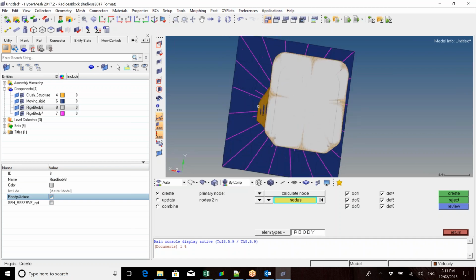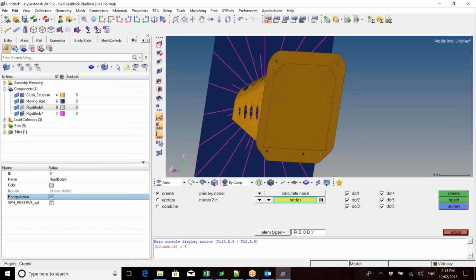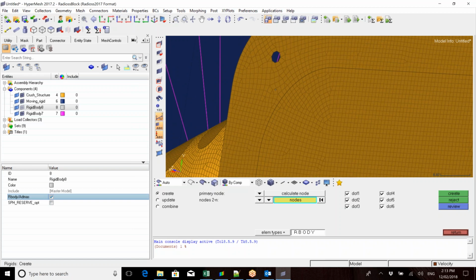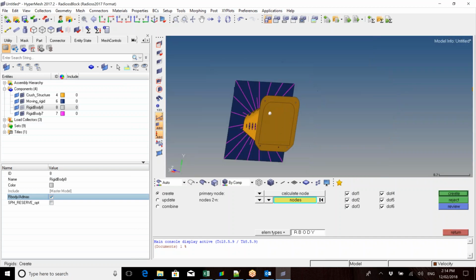So for this as well, the rigid body on the back of the crush structure is connected only on this side plate here. As you can see, there's an edge flange when the screen comes up. There's an edge flange here around the edge of it, and you can see the line there because on their structure this is actually enclosed in. So I've only rigidized the very edge of it, but when doing this, making sure that you set it up correctly for your vehicle, and correctly if it is properly specified in the FSA rules, is a big point as to where these rigids would be set up. So making sure that you know exactly where they're meant to be is a really big thing. Otherwise, your results can be completely wrong. I just want to make clear that this is how this case is set up, but for everyone else, it could be slightly different.